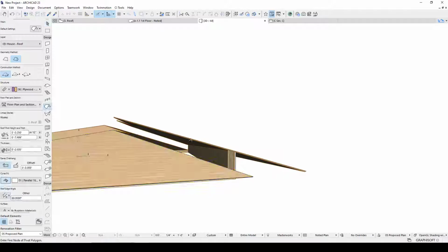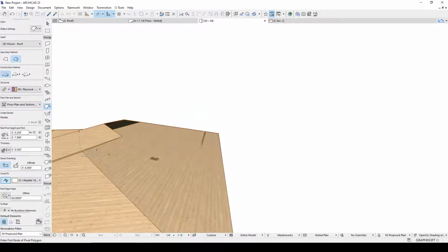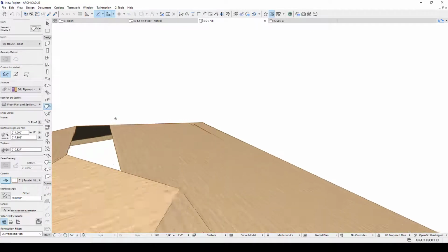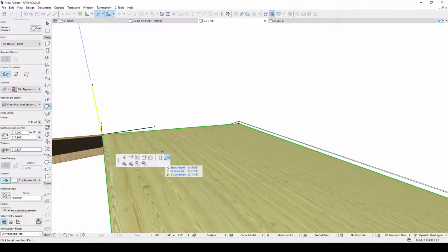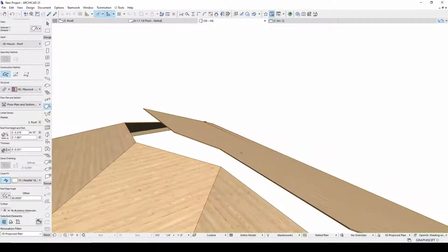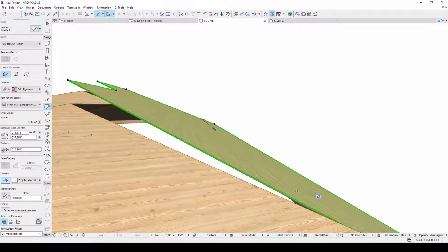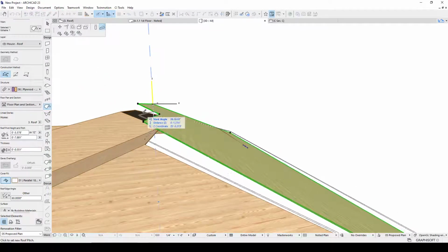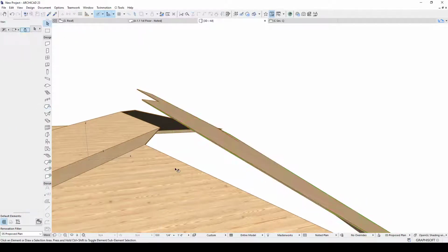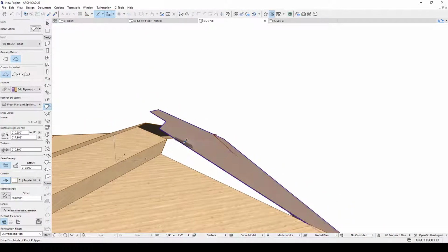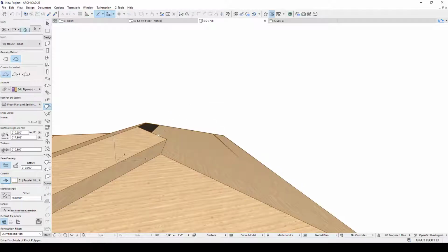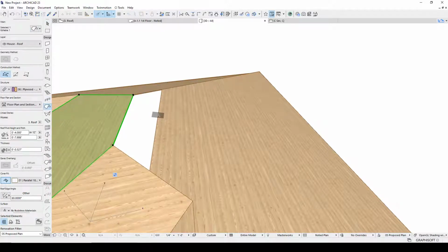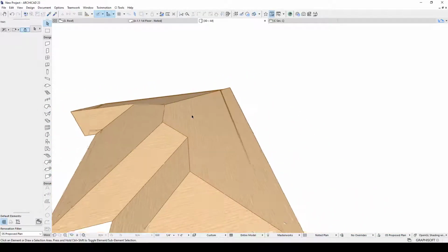So let's take the properties of this and inject them in that. That gives us the same elevation on our pivot point. Come over here and grab this, and then you can see what I'm doing. I'm just hinging off that pivot point, but changing where it hits. So this can sometimes be useful. If I want to just get it back to the same pitch, I can inject those properties. I can select this roof, select the roof tool, hit control, and close that up.